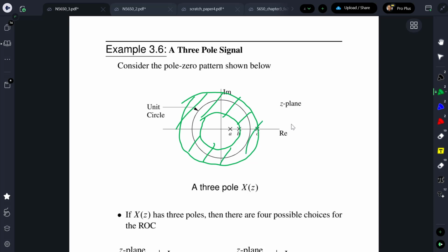So if that's the case, if we're between B and C, then what's the direction of A, B, and C sequences? Assuming A and B are right-sided and C is left-sided? Right. Does everybody follow that? Because we have an exterior that departs from B, so A must also be a right sequence because it's inside of it, so it's going in the same direction. And then C must be left-sided because it's pulling in. It's the smallest pole radius of the left-sided sequences.